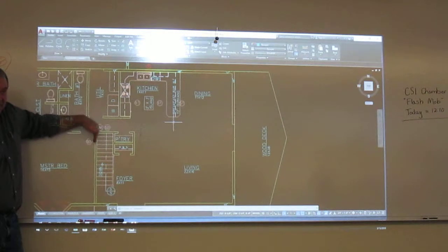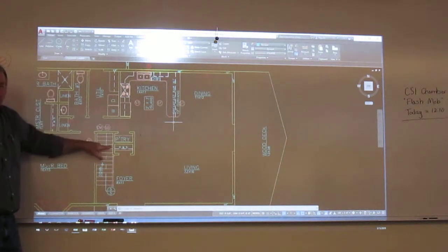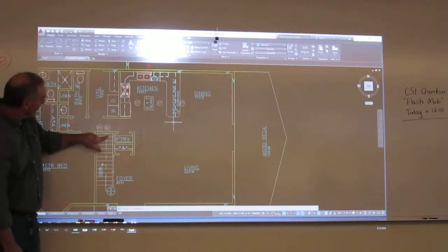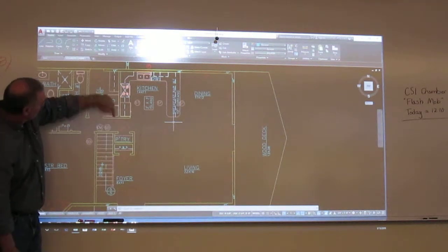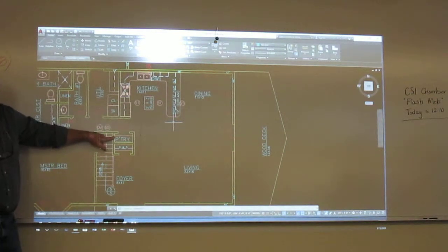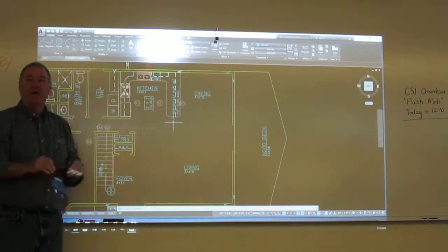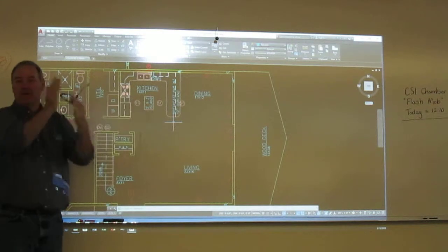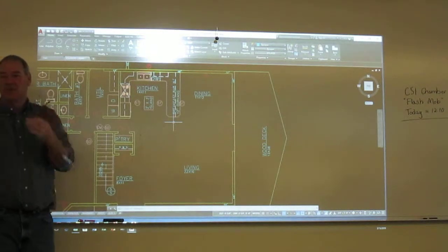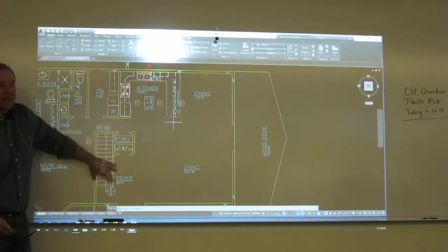Now this is almost 4 feet. There's just going to be a couple trusses in here, but it's still a zone. Okay? And it's going to go flat from this wall. Okay? So I need to have that zone delineated, right? If you look on page 551, see where they've got that center line? That's showing, hey, all the trusses in this zone are here, then we use the center line, and then when we switch truss shapes. Okay, these are standard trusses right here.